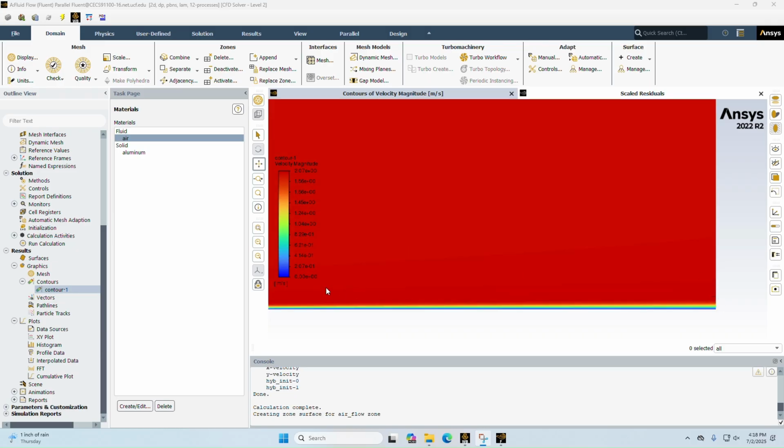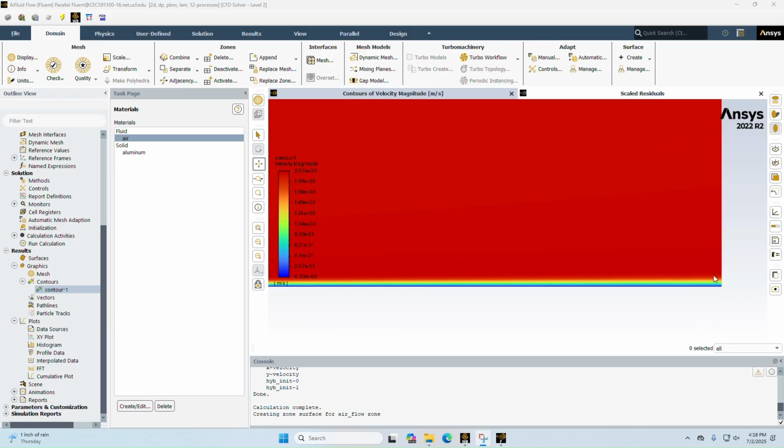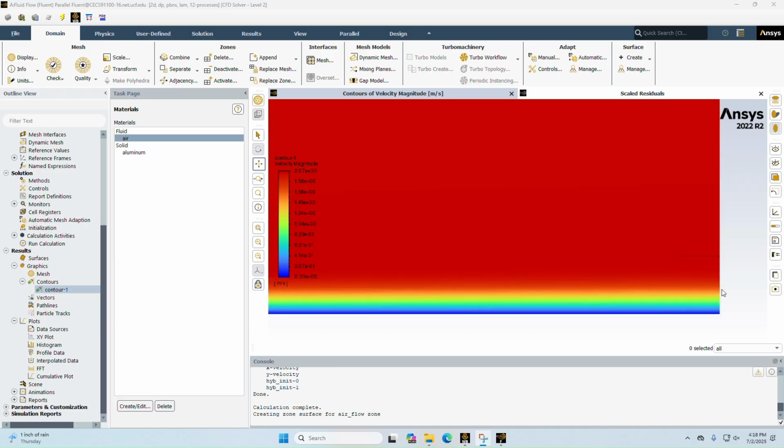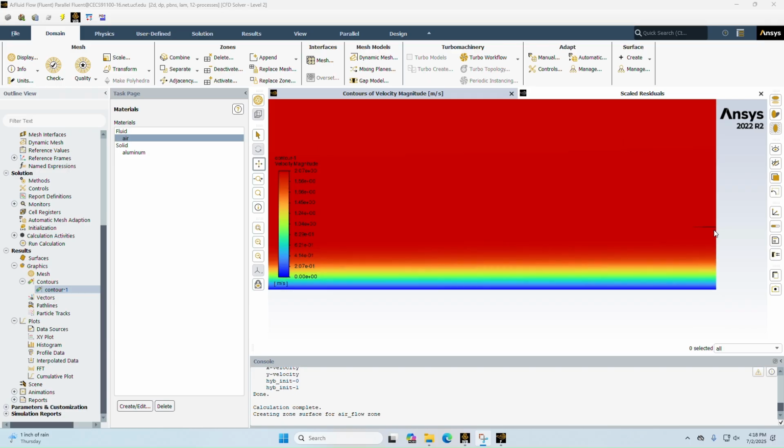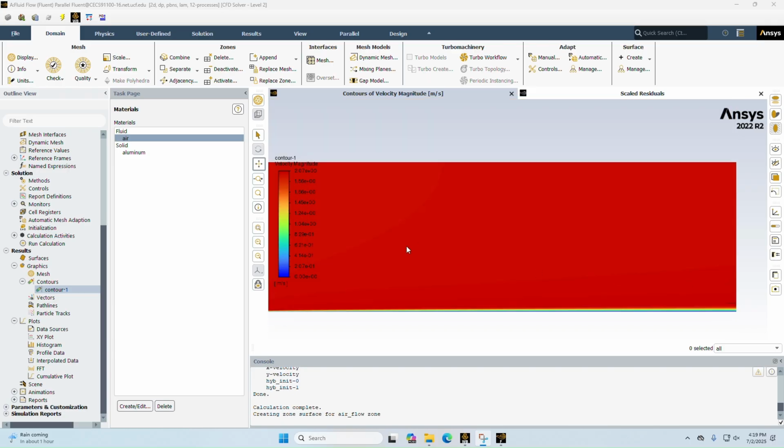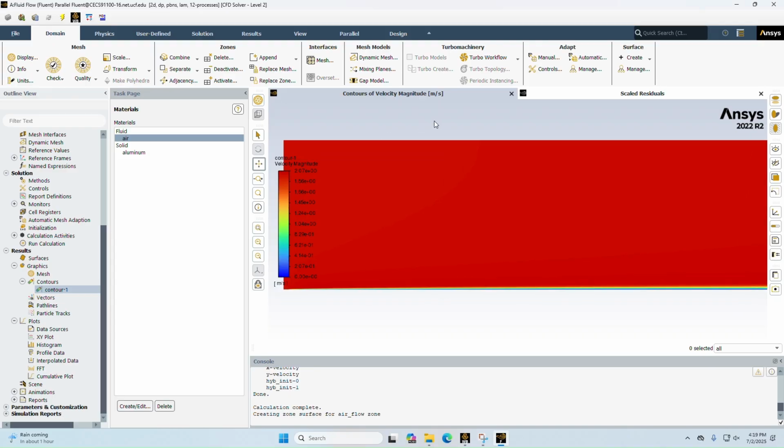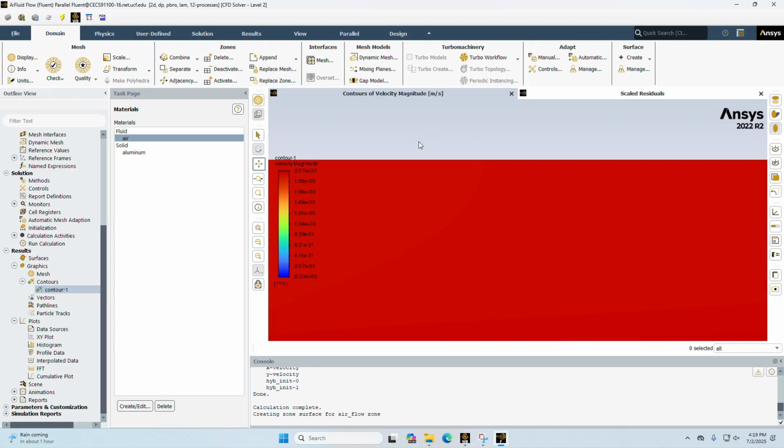The boundary layer is where there's a difference between the maximum velocity, which is 2 meters per second, and it goes barely below 2. So wherever that line is, that's where our boundary layer is. You can see it's slowly increasing in height as we get further along, and it's a little bit more clear now when I change the velocity.